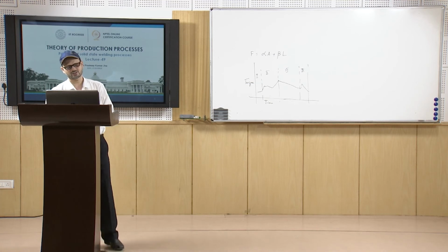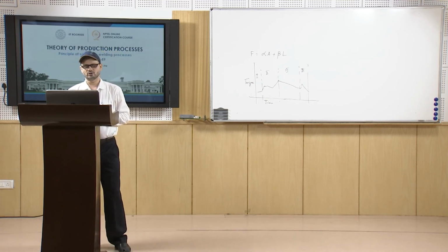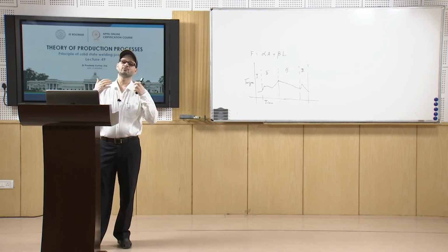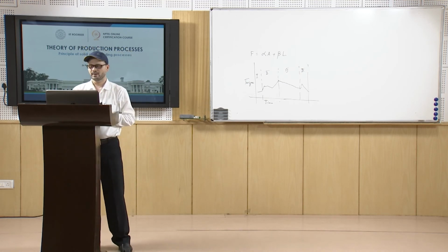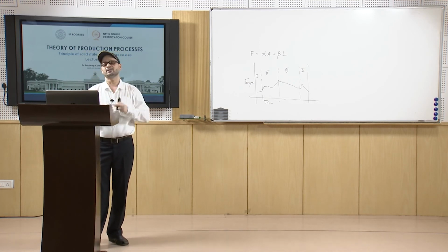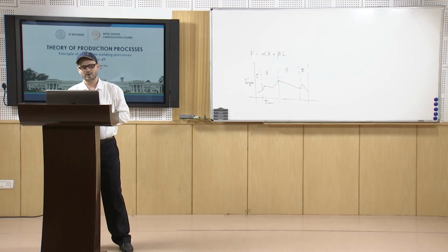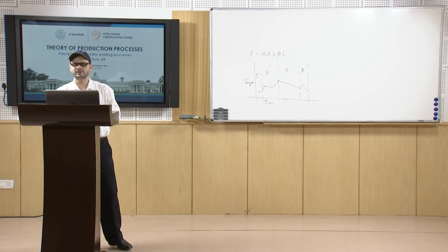Now, in this case the heat will decrease, and you will have an increase of torque also, and there are certain welding variables like the inertia of the flywheel and the speed of the flywheel. These are the variables which affect the quality of the weld. So, these parameters are to be seen.